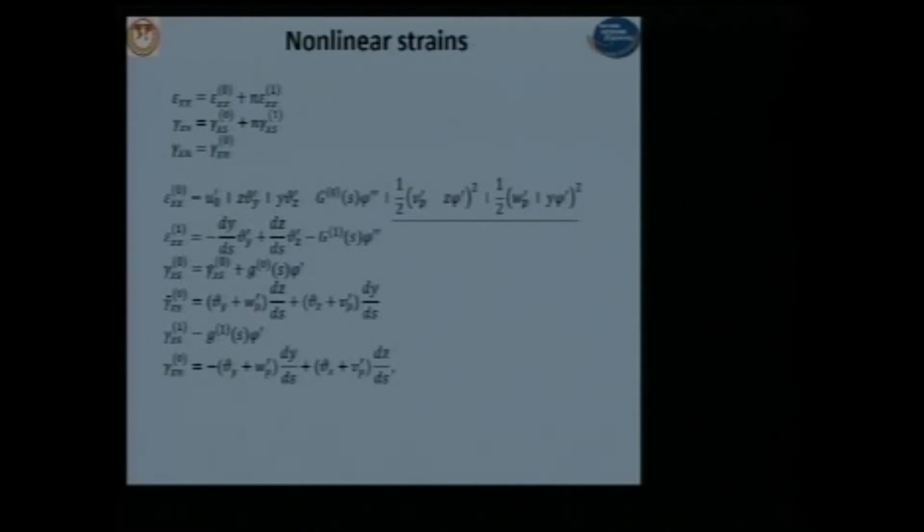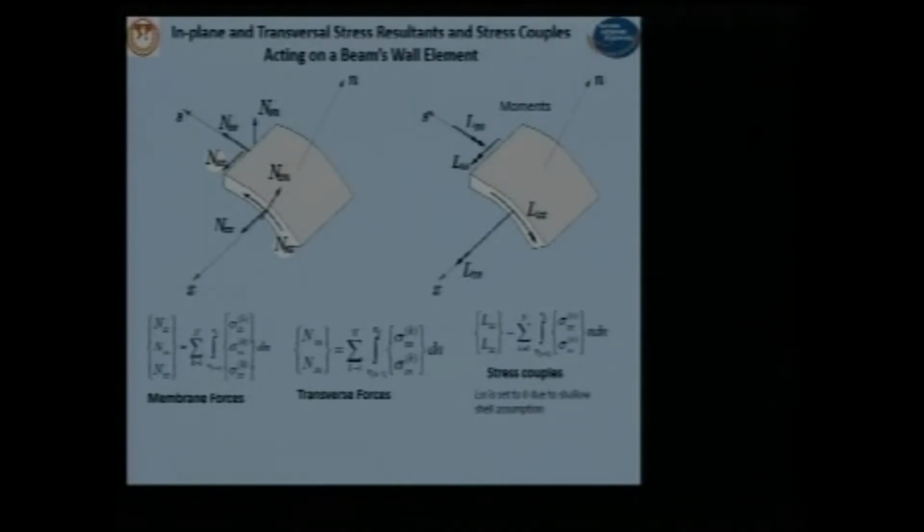And we have also a warping function of the first kind. It means that it's warping of the midline of the profile, which is warping of the general profile, and a warping function of the second kind, here G1, which is warping due to the thickness of the wall. This is another warping. And finally, we are taking into account the number of layers, n plies of the composite, and integrating through the thickness of each layer, we get membrane forces.